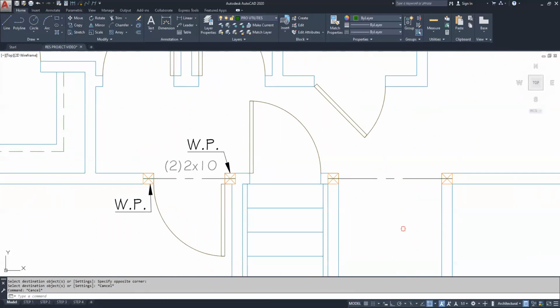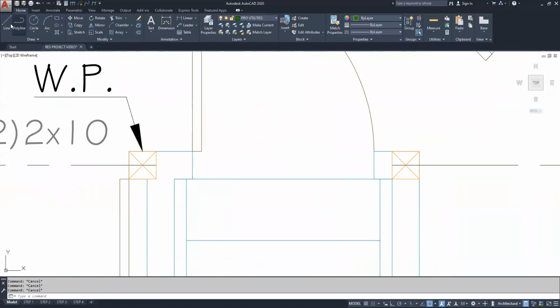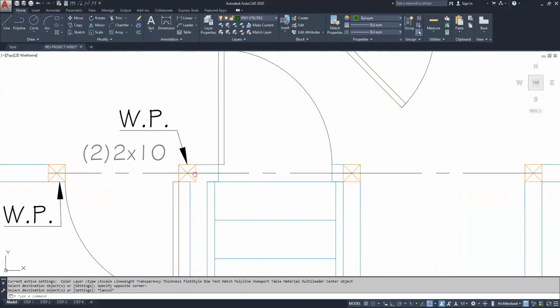So that's probably the safer bet. But as you get more experience under your belt, you can start to try to make your own decisions about stuff. Like right here, I'm going to make a decision that I'm going to just use these same posts for another header right here. So I don't have to build another post.